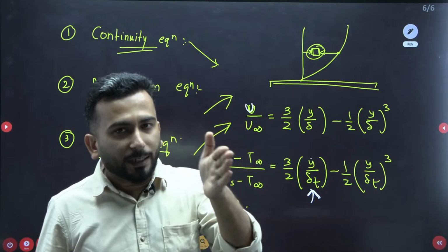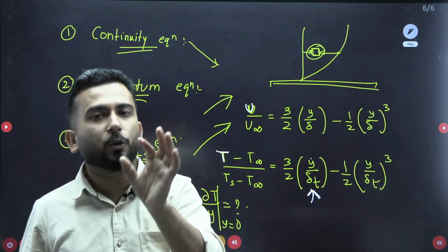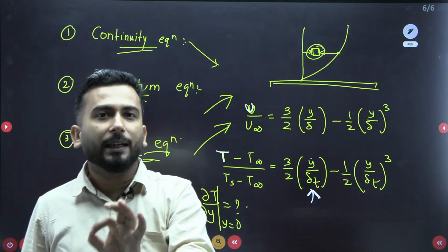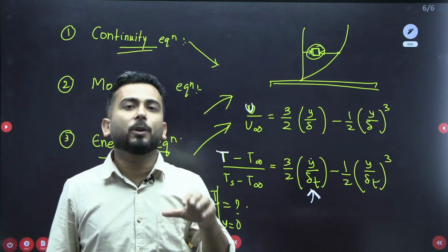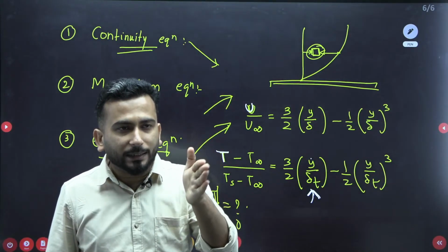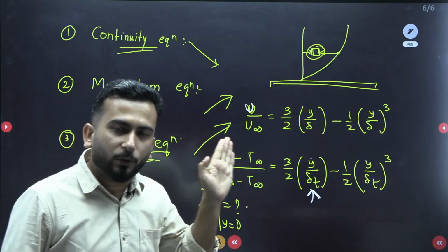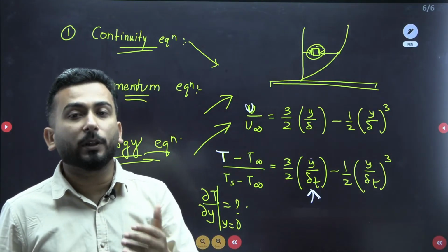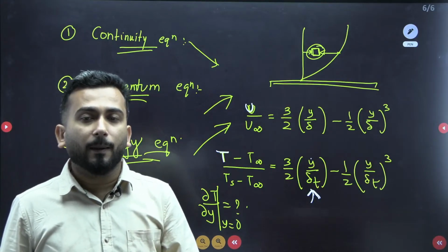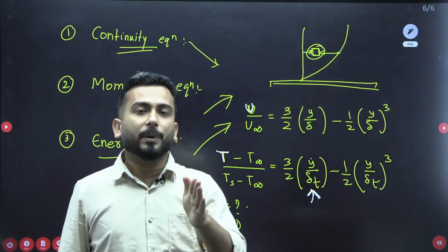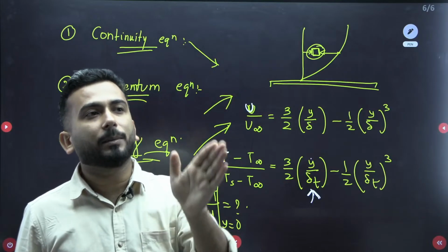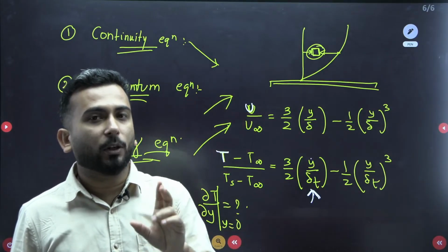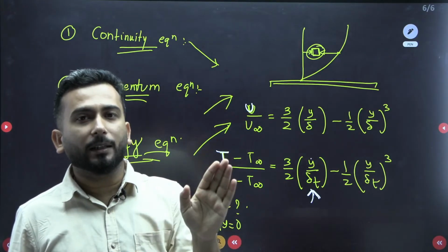Because at different positions your h is changing. It is a local phenomenon. At different places across the flat plate, when you travel, your h value changes. When your h changes, your heat transfer also changes. For example, I want to know the heat transfer at some different position. You cannot take the same h value everywhere.